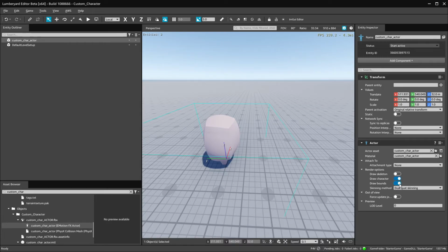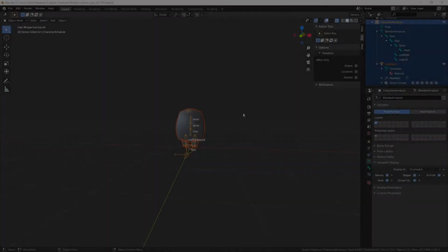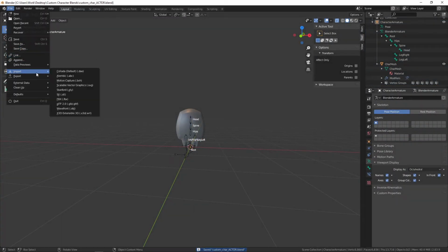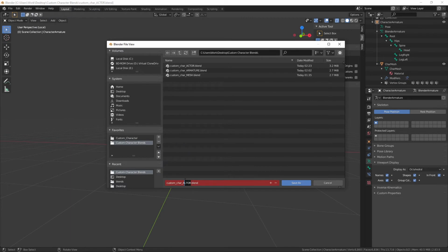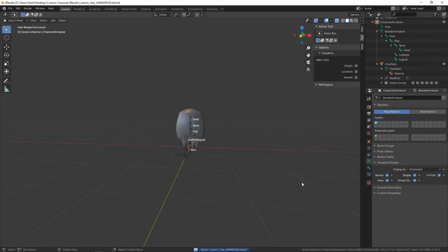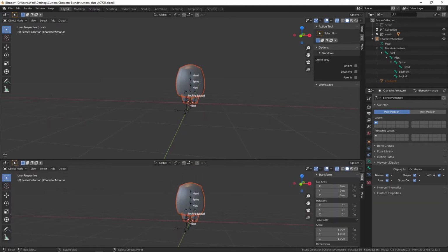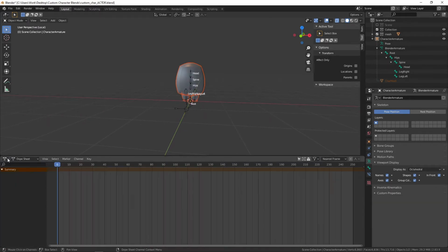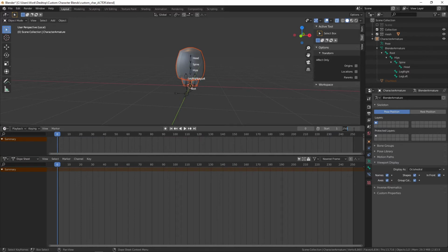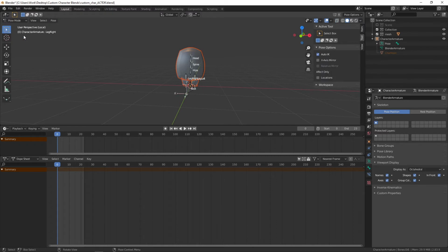We'll head back to Blender now and create an animation to import. First, I'll save the actor and then save a copy to hold as a base for the animation. The mesh will be nice to have to look at while I'm animating, but won't be exporting it, so I'll move it to a different collection and hide that as necessary. I'll create two new windows for the dope sheet and timeline editor, and I'll set the timeline editor from 0 to 23 frames for a 24 frame animation.